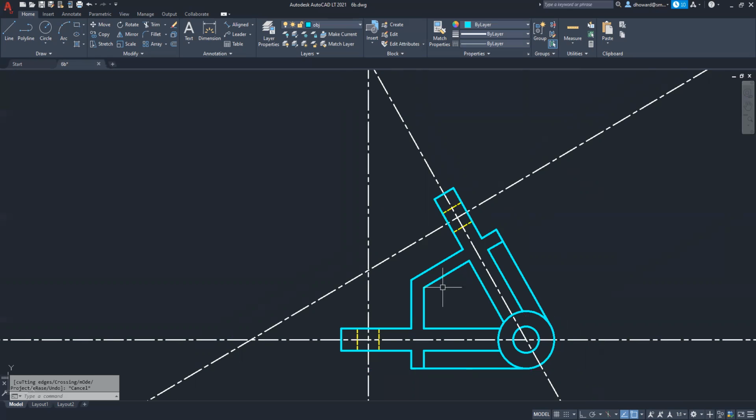But the fillets inside here, inside this web, and on the outside here, they are dimensioned otherwise. They are all dimensioned as 1/4 of an inch. Let's do those first. So F, enter, R, enter, 0.25, enter. And we're just going to hit this whole thing. All right. All 1/4 inch. And these guys as well. Those are also 1/4 of an inch. I believe that is it for the exceptions.